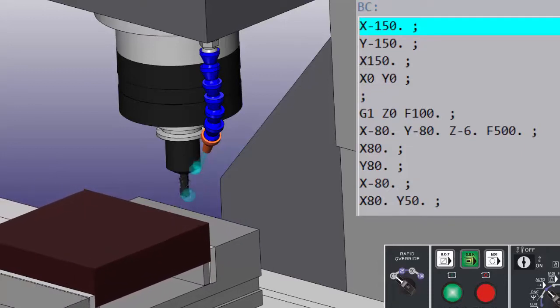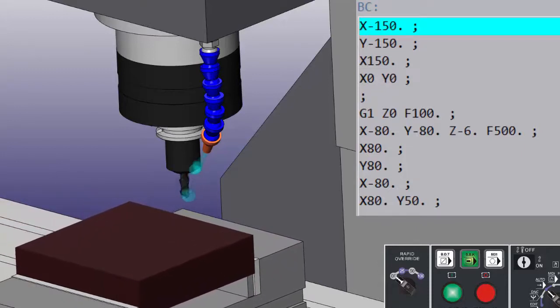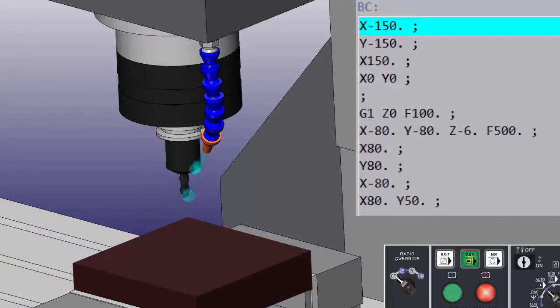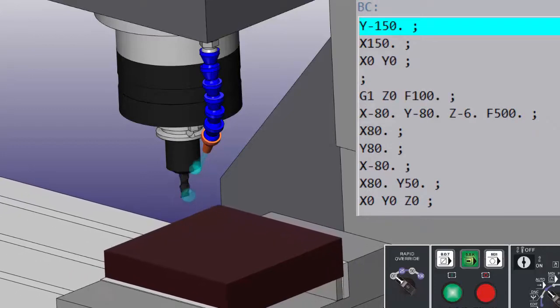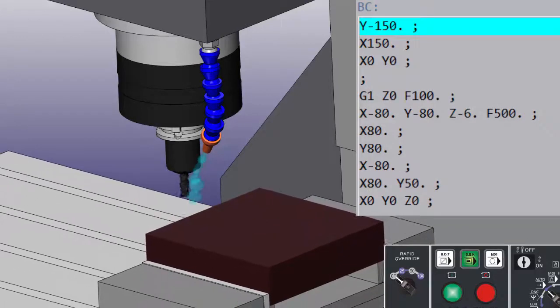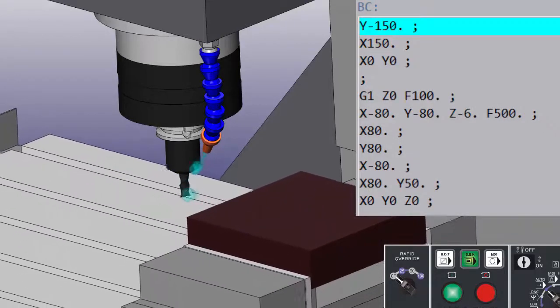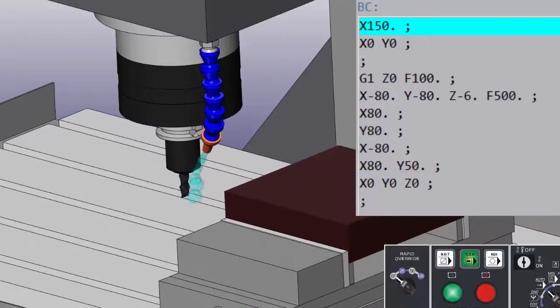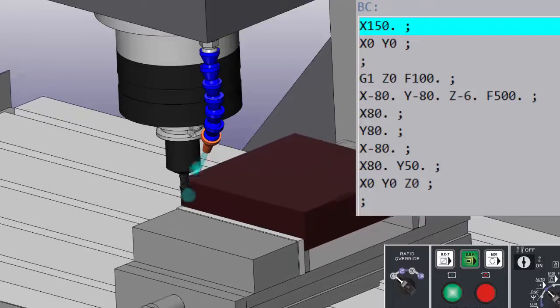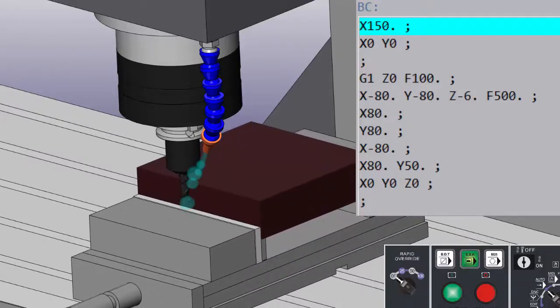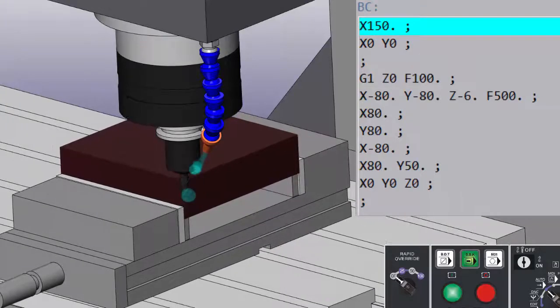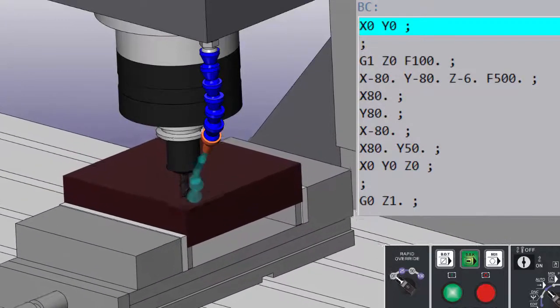Now I'm just moving X. So I'm saying X minus 150. So it's not moving the Y. I'm not programming a Y move. I don't need to because it's not moving Y. You could repeat the Y, but I definitely don't recommend that you do. You just put in the axis that you move. This is just stupid. It's not actually doing anything. It's just rapiding around. I'm just showing you. And then I'm going to rapid back to 0. There. And there.